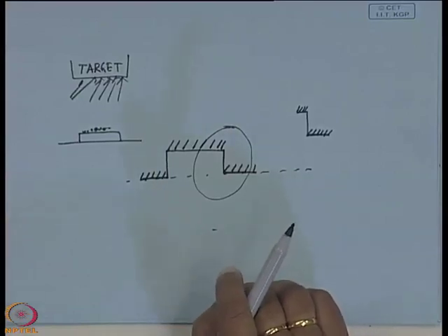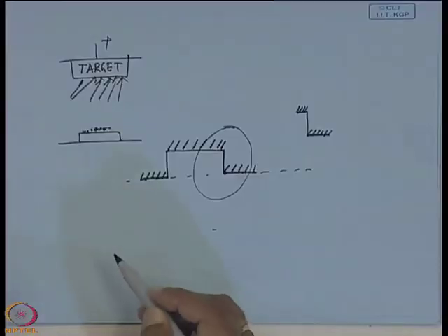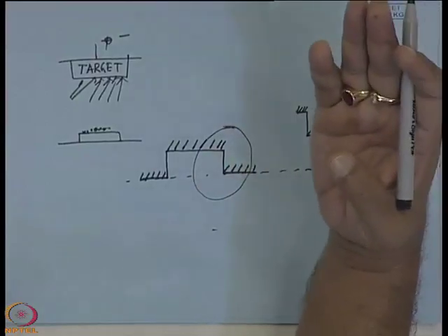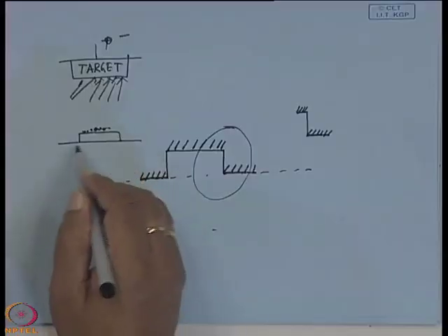Right. Now, you can ask me, sir, why do the argon ions move towards the target? Because of the potential, yes. It is always kept at a potential. Okay. Sorry, negative potential. So, the neutral or the positively charged particles will move towards that end. So, it will collide with that, and a large chunk of the material will be removed from the target and will fall on the substrate to give a film type of appearance.